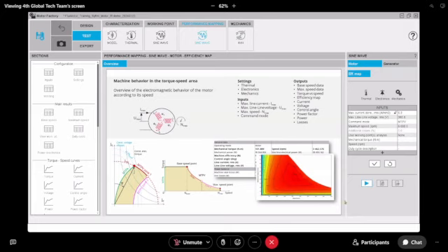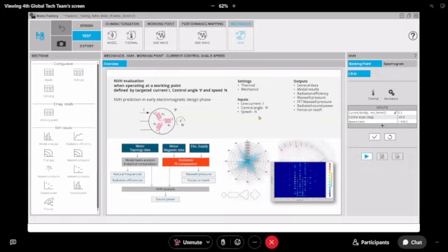And if you have a duty cycle, you can put it on it. This is an important test as well because you will see the maximum performances of your machine. And then the last test available is the NVH. The NVH test here is really helpful in order to choose one candidate because you can have 2, 3 candidates. Magnetic and thermal are okay, but which one is noisy? This is something you can choose directly and compare through the mechanics.